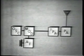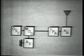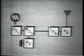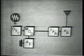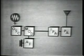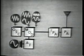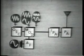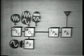Looking at the simplified block diagram of a conventional AM transmitter, let's change it to operate single sideband. Of course, we use a crystal oscillator of low frequency RF to generate a stable carrier. When we modulate it with an audio frequency, the two signals are mixed together in a balanced modulator, which is designed to cancel out the carrier and filter the modulating frequency in its output and produce only the two sidebands, the upper and the lower.